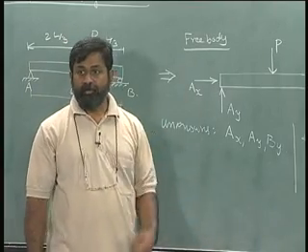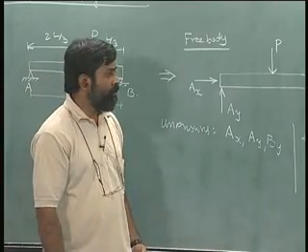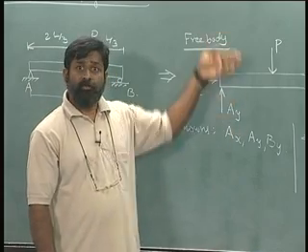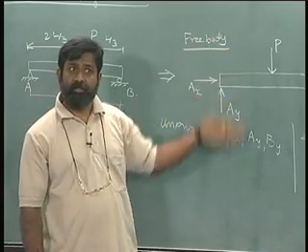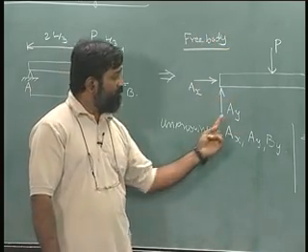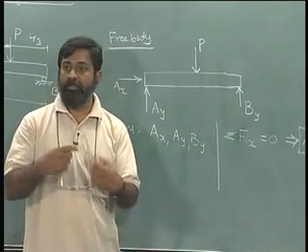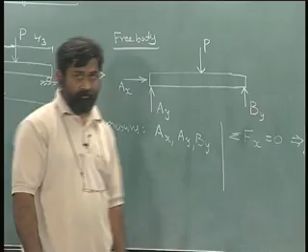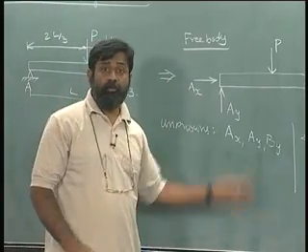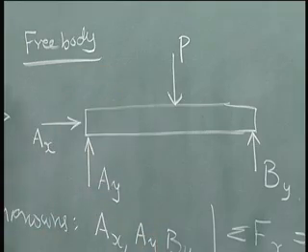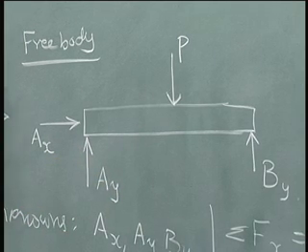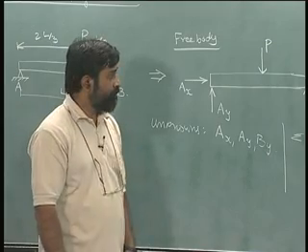What is the next step? I could probably go for the net force in the y direction equal to 0. That will involve Ay and By. This is where we use a simple trick. Instead of going for the vertical component of the net force being equal to 0, let us look at any other option. We have the moment equation that is possible.